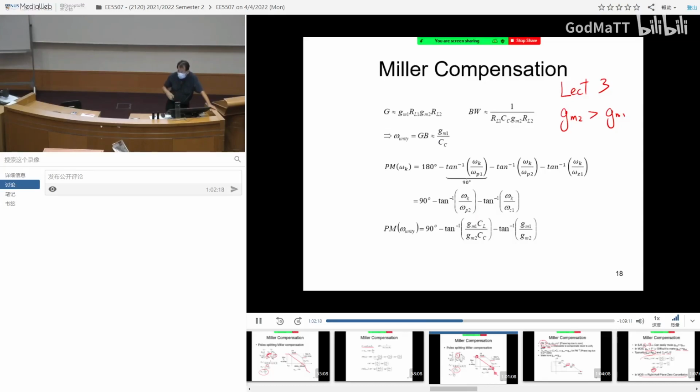At that time I told you, we always use that, but just accept it as it is. I never explained. Actually, looking at this guy, now you know why. If gm1 is less than gm2, for this phase margin, you are going to have arctangent of less than 1.